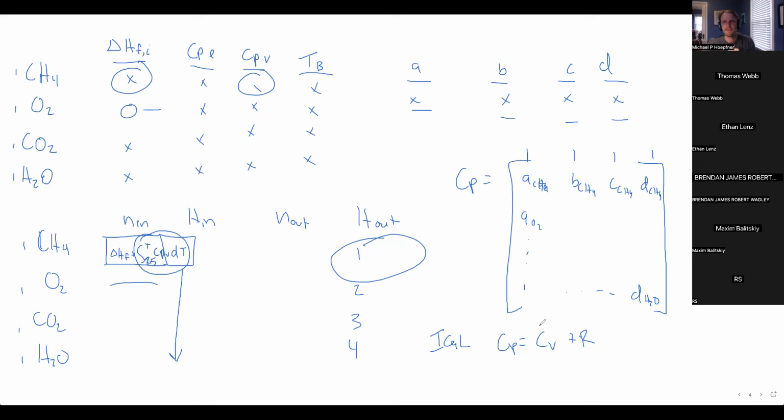In a real world setting, is it a reasonable assumption that liquids are incompressible? So a change in pressure wouldn't correspond to a change in specific volume? It depends on how big the pressure changes are. If I'm talking about 10 atmospheres of pressure, I don't care about the density change of water, right?